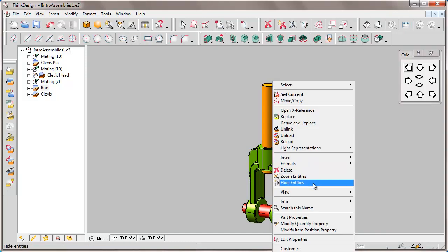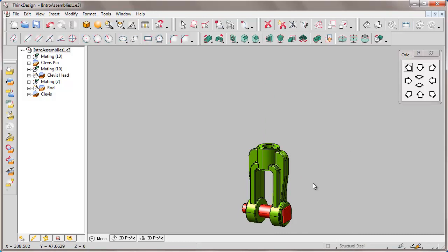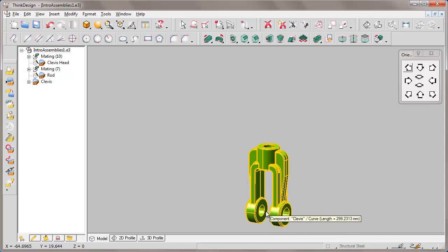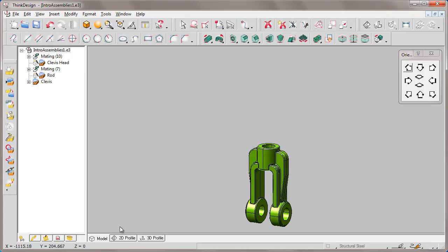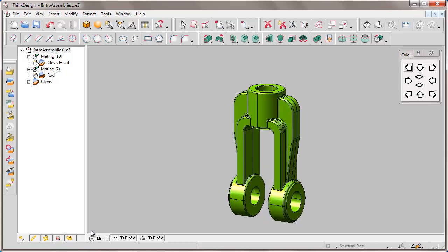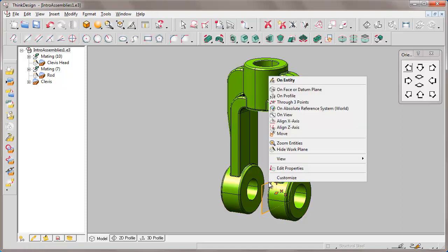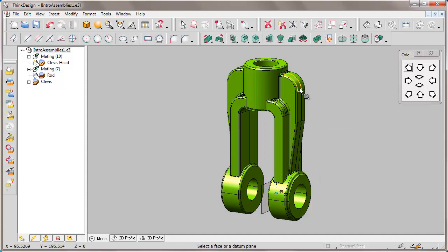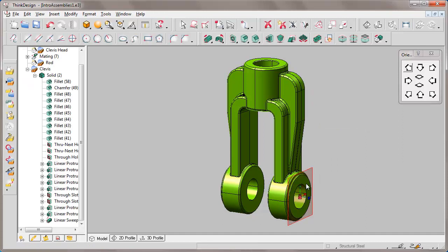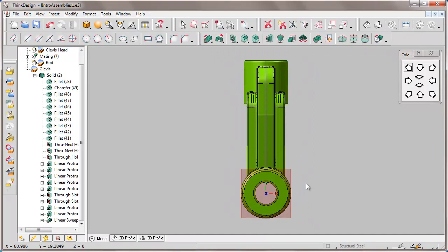It's another approach. In actual situations, we use both bottom-up and top-down because some parts may have already been created and we can insert them, while we must create other ones from scratch and save them. In the meanwhile, to show the parts we are interested in, we hide the head and rod and cancel the pin to create a similar one that will make a next reference, and move the work plane to one of the two faces.